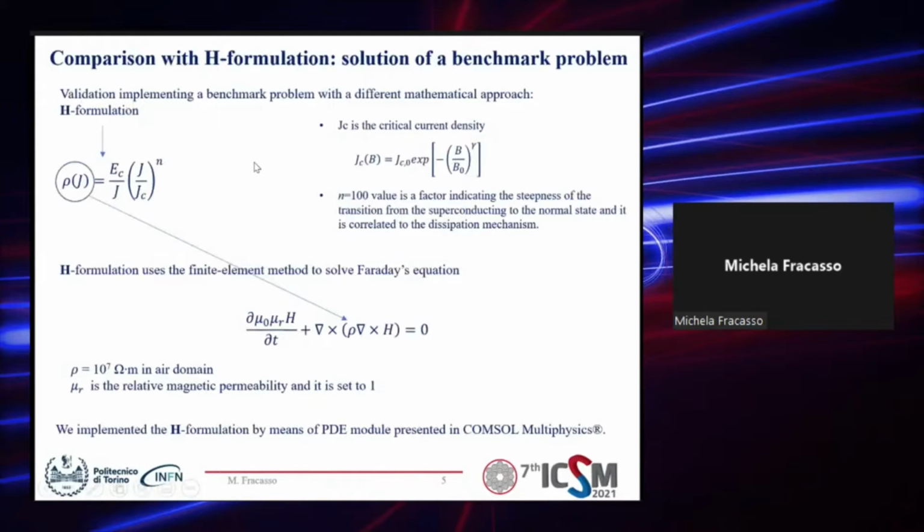Also, in this case, we implemented the H formulation by means of COMSOL Multiphysics, in particular with the PDE model. Using the H formulation, the power law is used to describe the superconductive behavior. Also, in this case, the critical current density, Jc, is expressed as this exponential equation, and we set n to